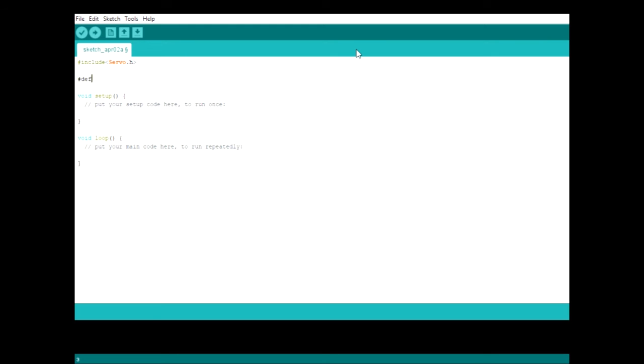We are going to use the servo library to control the motor, defining maximum and minimum for the motor, that is 2000 and 1000 respectively. Pin 9 is for the motor, pos is to store user input, creating object BLDC of servo. So starting serial with baud rate 9600. First we need to calibrate the ESC. To calibrate an ESC, set the throttle to full and then to 0.